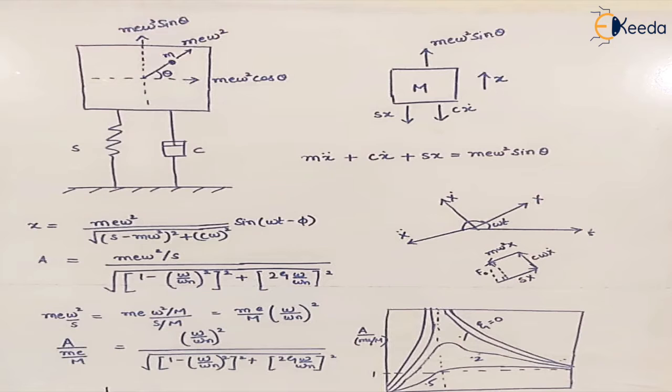Now we already know that in all types of rotating machinery, maybe an electric motor or a turbine or a pump, there are always some unbalances. And why are these unbalances there? They are because of the rotating masses in the body. We have already discussed the balancing of rotating masses in another chapter. And the unbalances left in the rotating bodies produce vibrations in the system.